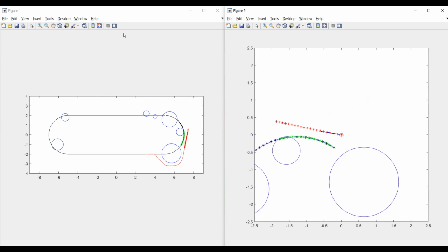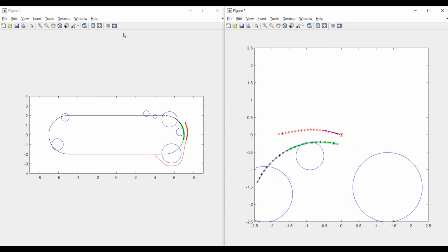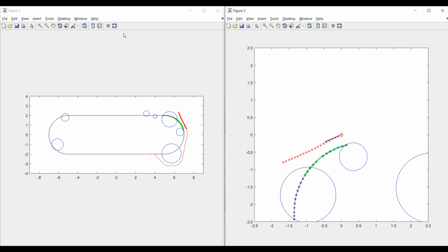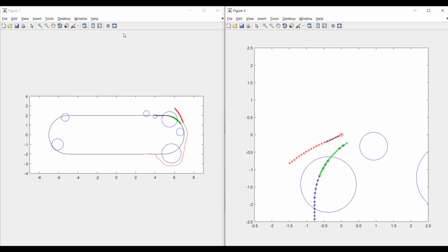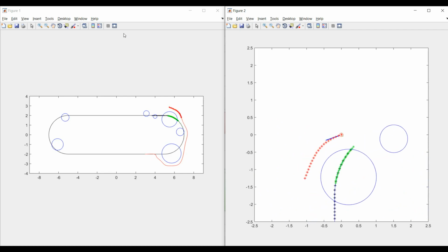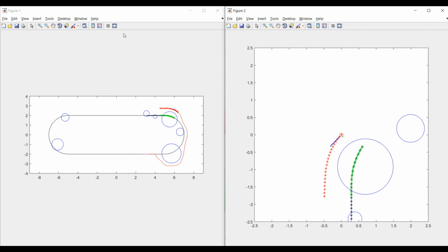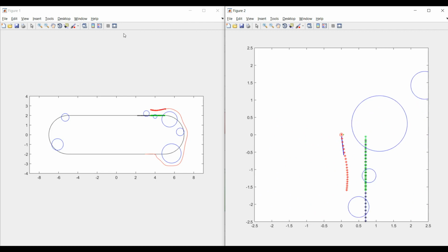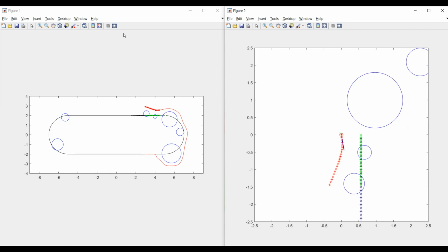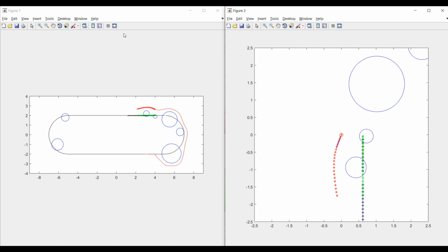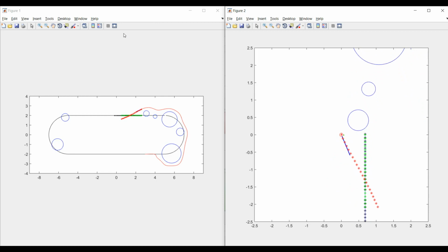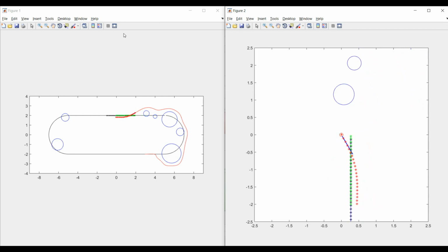and the blue arrow that we see on the right is the current velocity direction, while the small green line that you see sometimes is the current inclination angle of the robot. The green points are the corresponding path points that the MPC is internally using for computing the path following cost. And these are adaptively moved along the reference trajectory or the fitted reference path to match with this path following formulated optimization problem. And we see how the MPC is capable of navigating around these obstacles.